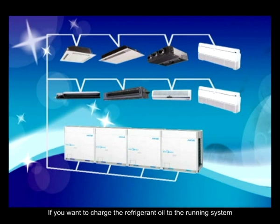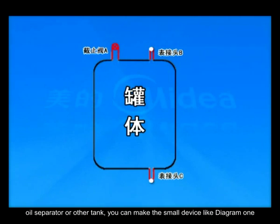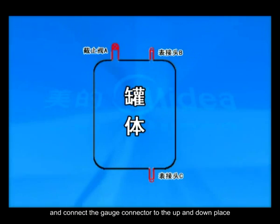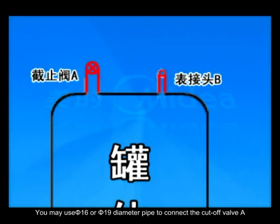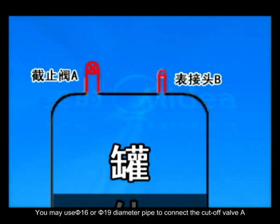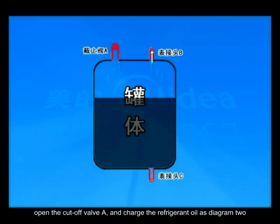If you want to charge the refrigerant oil to a running system, you can try this kind of small device. Using a small refrigerant tank, low pressure tank, oil separator, or other tank, you can make the small device like diagram 1 and connect the gauge connector to the up and down place. You may use Phi 16 or Phi 19 diameter pipe to connect the cutoff valve A. Open the cutoff valve A and charge the refrigerant oil as in diagram 2.